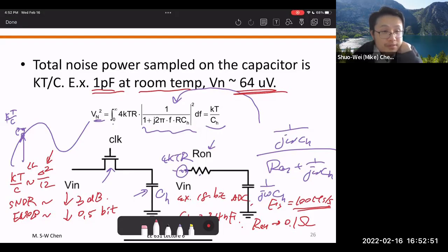So in that regime, you don't even really care about this noise. I mean, it will be there. I shouldn't give you a false impression that it's not there. It is there. It's just that it's negligible, right? Does that make sense? So to that extent, you basically don't care. But it will be there. So it is always the high resolution. When you design ADC for higher resolution, that's where you normally would care more about this kT over C noise.